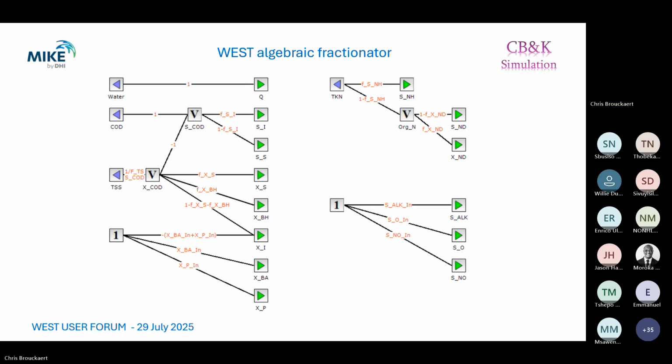You get negative concentrations of components which are physically unrealistic, so sends the model into limbo, and sometimes causes numerical problems, and so when we tried to use normal plant data, we would find that the simulation would often just crash.